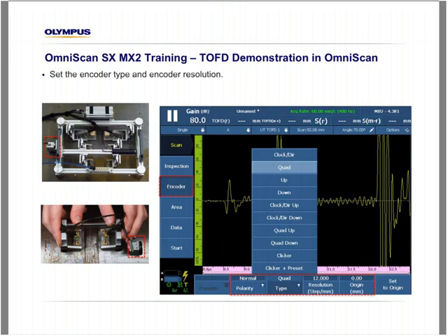Under the same scan menu, the encoder parameters: most encoders commercially available, and all of the ones from Olympus, are quadrature type encoders. This is a hardware function. The encoder resolution can either be calculated by a wizard under the calibration menu or entered directly here. The normal operation would be to drive the encoder a fixed distance using the manufacturer's encoder resolution and validate that it has driven a specific distance within a certain tolerance.